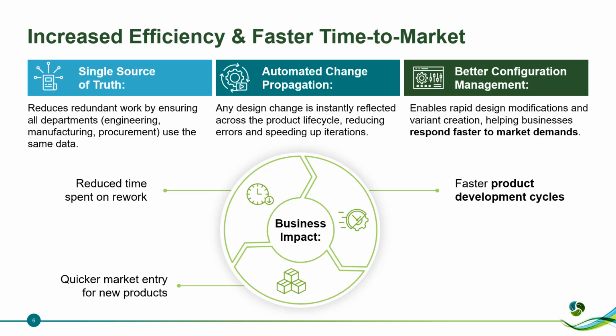Automated change propagation. This is important because in the unified product structure, they went to a unified change governance structure as well. So you used to have an ECR and MCR. We used to have all kinds of different change objects or methods in the governance cycle where they weren't connected very well, unless you customized and things like that. So the change propagation or change management helps identify the effectivity of a change or the impact analysis, whether it's from manufacturing to engineering to product. You're able to see that thread across all of those much easier.